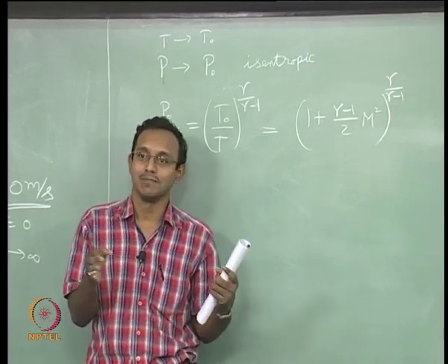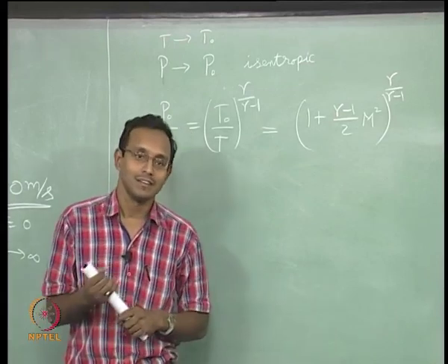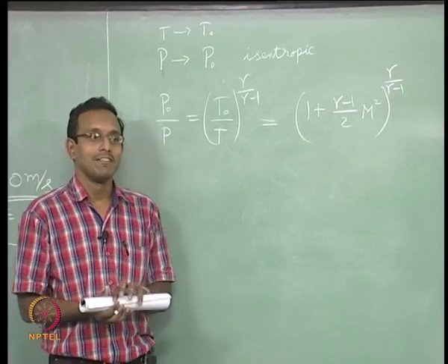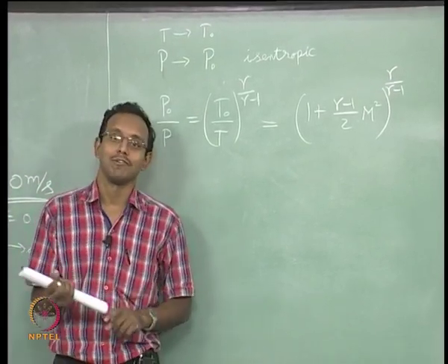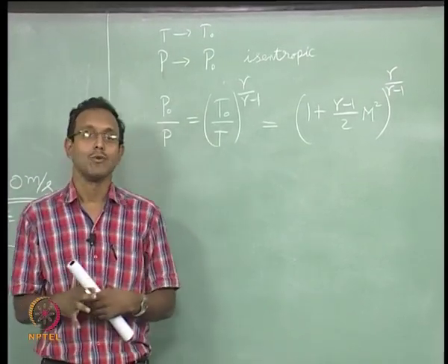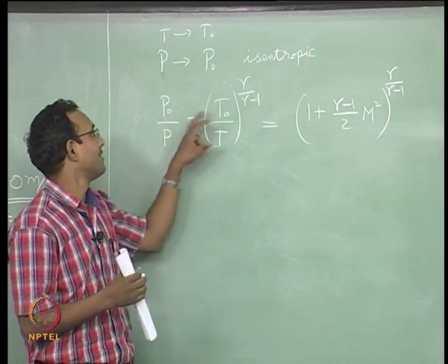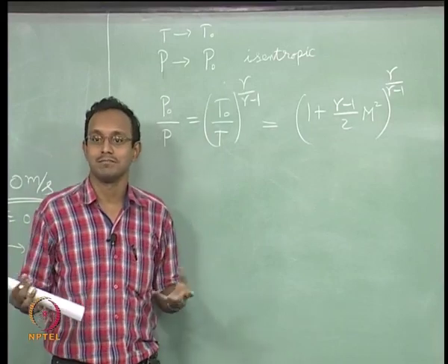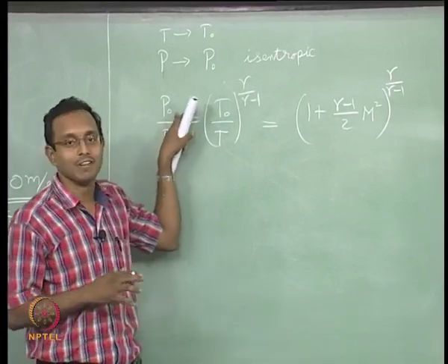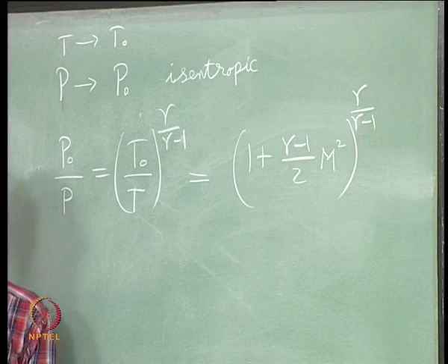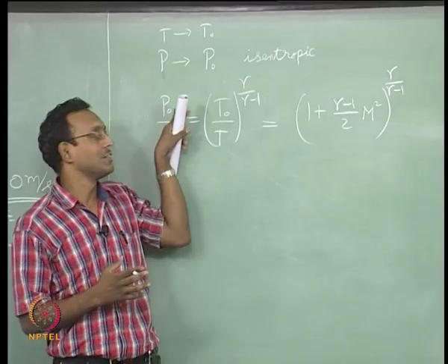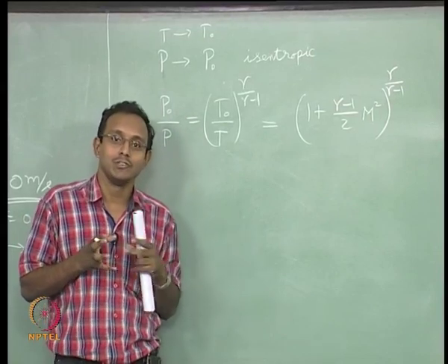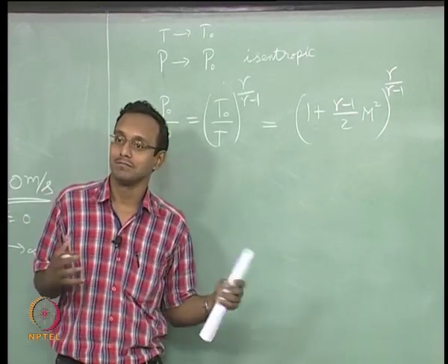Not all conditions will be exactly isentropic, okay. But anyways, in real flows you will never have any real stagnation flow ever, okay. So what they do is they use this as a way of finding out how much energy my fluid is having, okay. Pressure is a form of energy, right. PV work can be done from it, that is, pressure is just energy per unit volume stored inside the gas to do work in the form of PdV, okay.